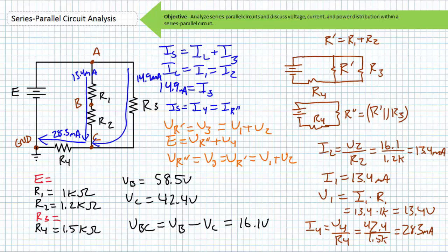Now we know both the voltage across and the current through the unknown resistance R3. Ohm's law states that R3 is equal to V3 divided by I3. Substituting in the necessary values, we find R3 equals roughly 1,987.7 ohms. If you're getting 1,979.9 ohms, it's because you're not listening to my advice about rounding only the final answer. Keep previous results and make use of the previous results during calculations.